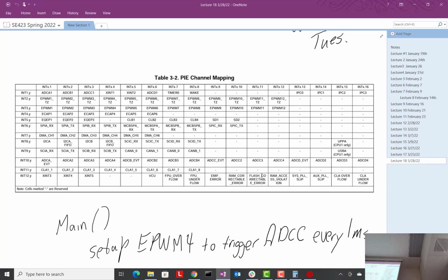All I've done is I've said that these three can be interrupted now by any of these other ones. That's the way I've set it up. Any of these other interrupts are not interruptible by anybody else. Once they're called, they finish before another interrupt can occur. But that's not the case for 1, 2, 3. I've set them up such that they have the lowest priority and they are interruptible.